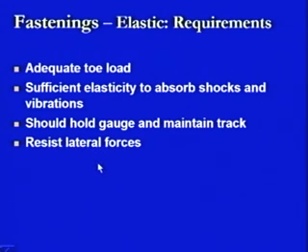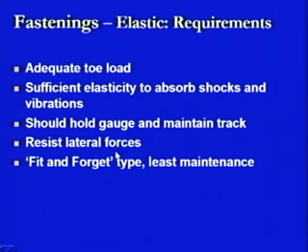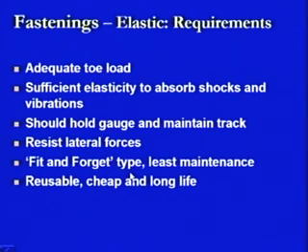They should resist lateral forces, whatever lateral forces are coming, because there are different types of forces, as we have seen when we discussed resistances and stresses. In that sense, these elastic fastenings should be able to take up all types of forces and especially the lateral forces. They should be fit and forget type, meaning the maintenance requirements should be as little as possible. Once you have fitted them in, we should be able to forget that we have fitted something. They should be reusable, they should be cheap and should have long life.